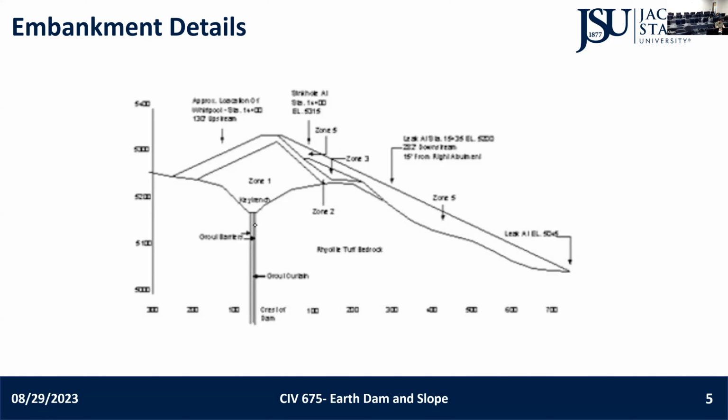Basically, each of the zones has its own purpose. It's not based on the availability of the material. You have different zones, and each zone has a different purpose. There are different types of failure for the dam, so you can do the design in a way that you can control each of the failures in a cost-effective way. It's like a modular design, kind of. And this is the best design.